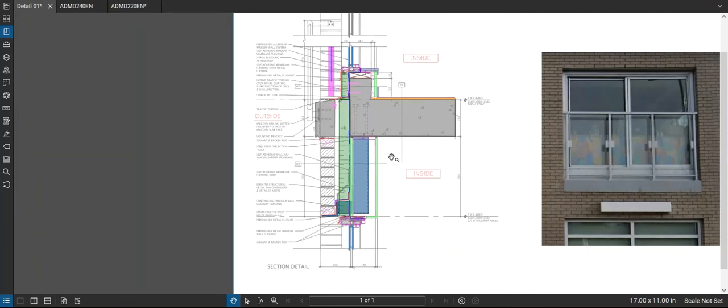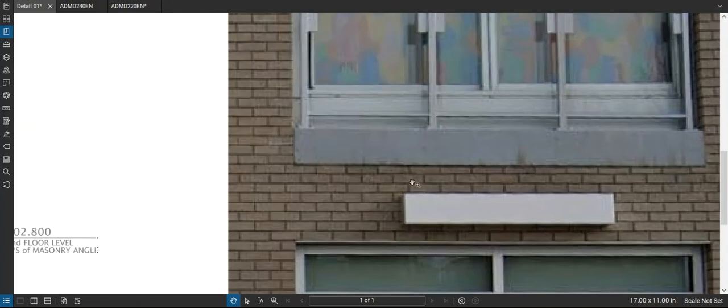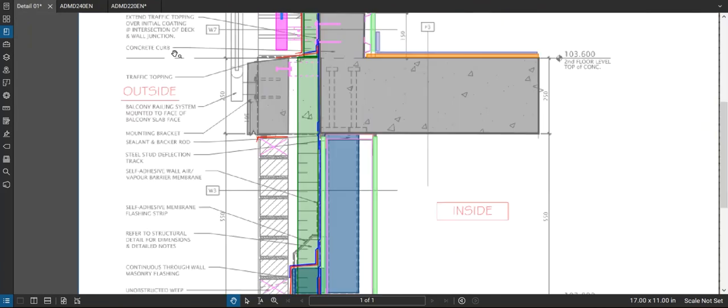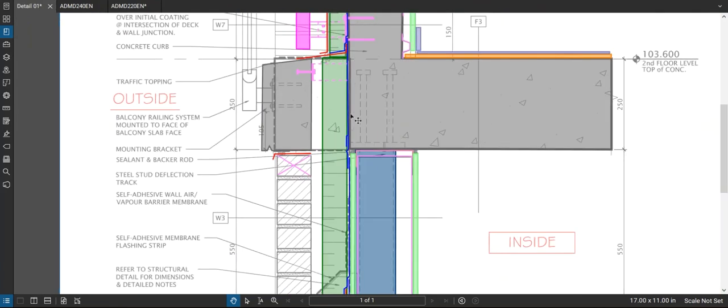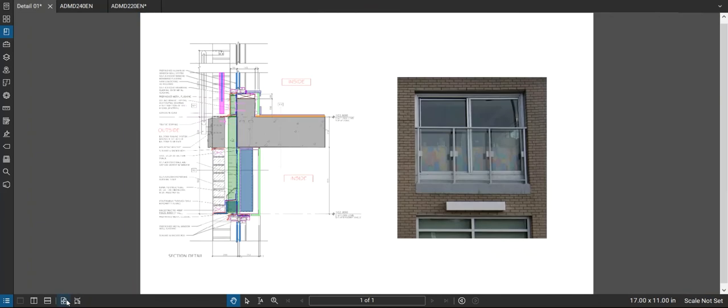And the other thing it did too, if you look here, I just noticed this, is the floor slab wasn't perfectly straight. So the brick started to get cut here, and I noticed that the brick are bigger on this end than that end. So by taking this approach, you have some more construction tolerance there as well to deal with that type of situation, or I guess, to avoid that situation.